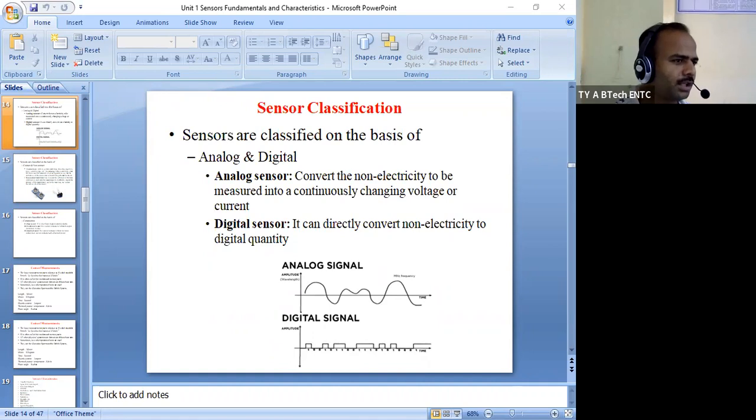But if you have done your earlier project for a sugar factory or grocery shop, measurement up to 50 kg, are you really able to supply the same design to the jewelers, with ranges from 10 gram to 50 kg? It is not possible. If you start with 10 gram, what happens with 9 gram, 1 gram, 2 gram, 0.5 gram gold? If you are not measuring, it will show directly 0 if your reading starts only from 10 gram or 1 gram.